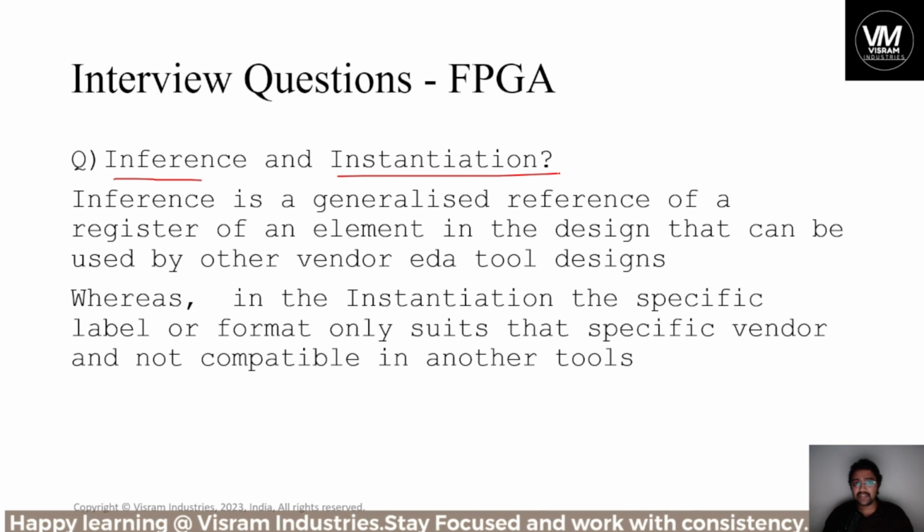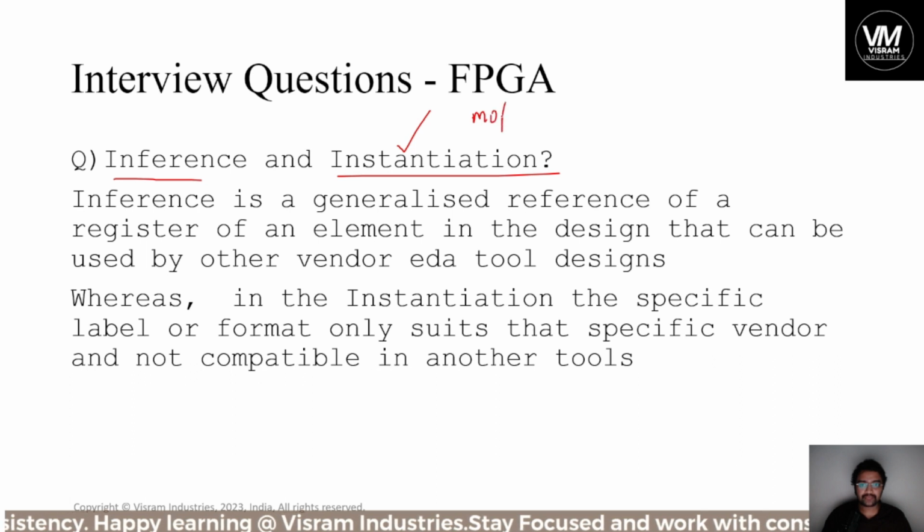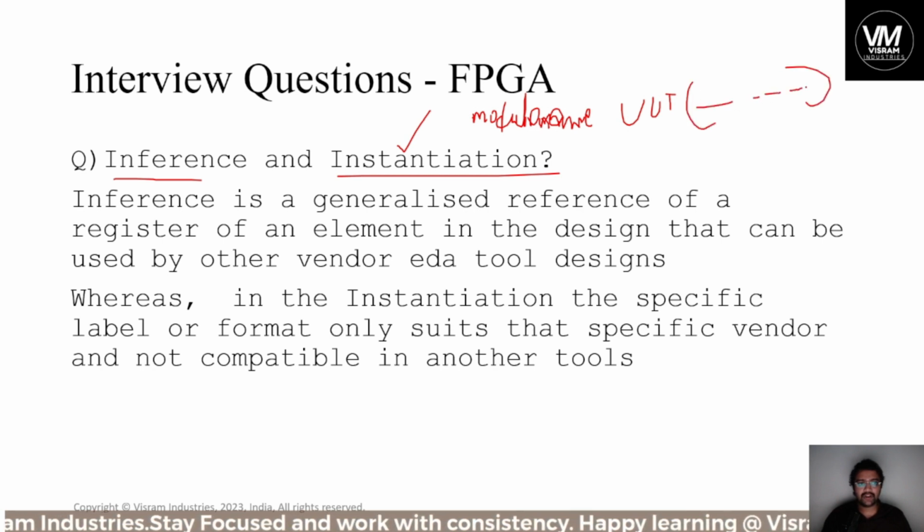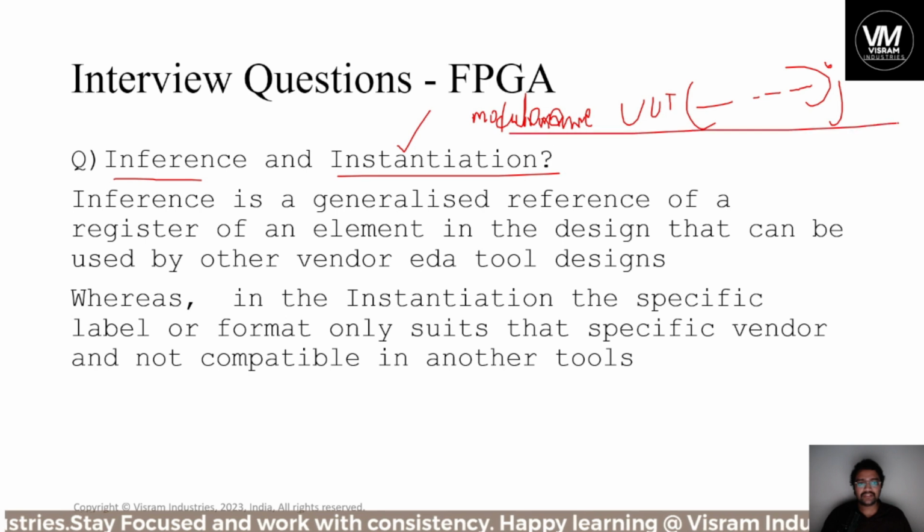Whereas in instantiation, whatever design you have made, internally that design can be used and utilized with a label in the test bench simulations. That is nothing but instantiation. Most of the time we instantiate the design in Xilinx or in EDA Playground in the test bench simulation. In the test bench simulation, we instantiate with the module name of the design. Imagine this is a test bench declaration module, and I have mentioned UUT, and inputs and outputs should be in the same order. So this is called instantiation.